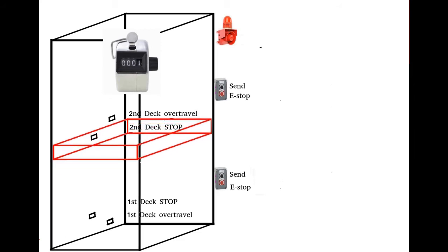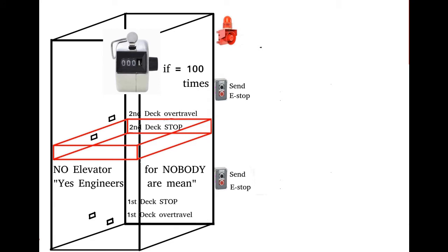And at every 100 arrival, we want the PLC to disable the platform operations until maintenance is performed and normal operations is restored by turning a switch key located next to the PLC. For maintenance, I included a manual up and manual down push button. These 2 push buttons allow technicians to move the platform without the restrictions imposed to the send button.